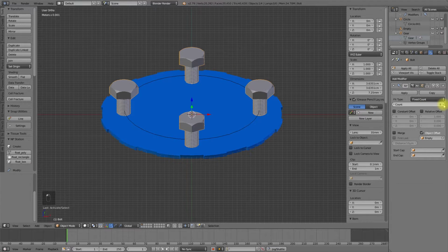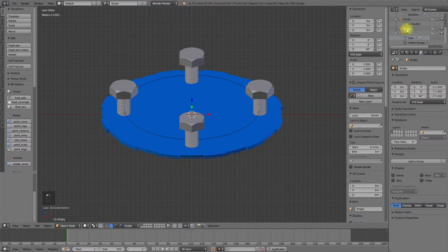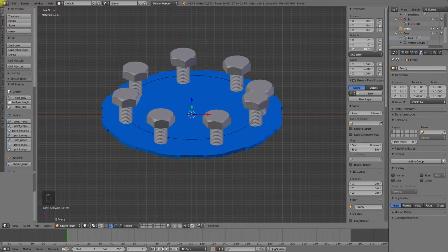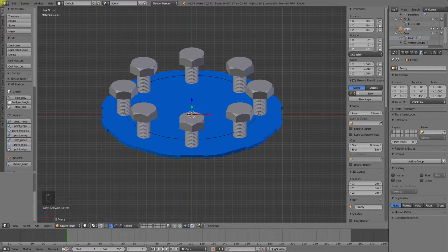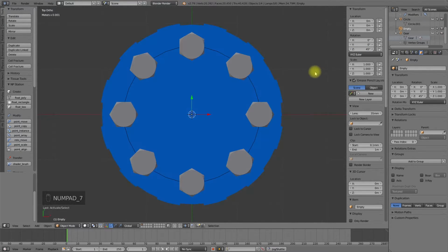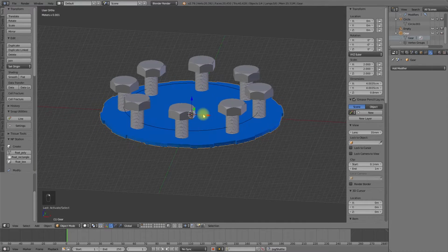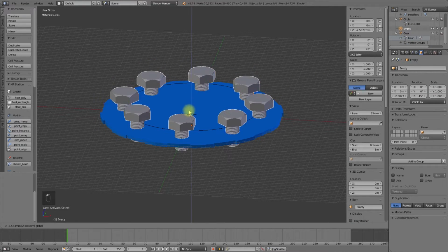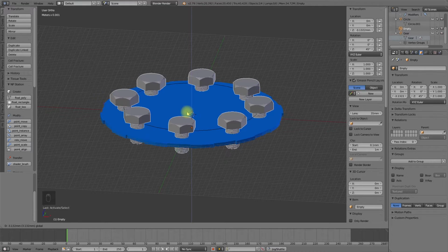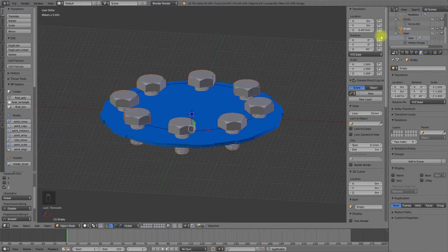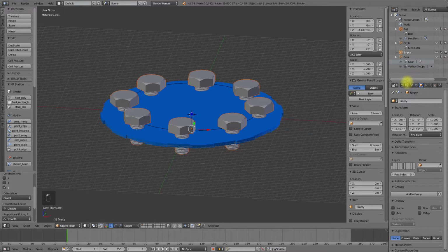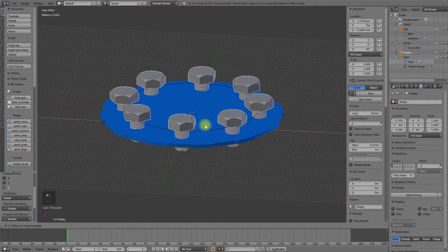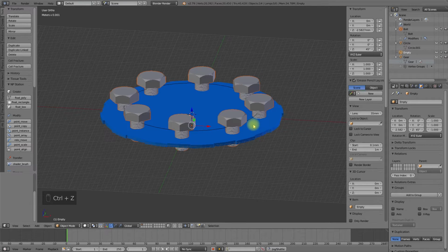If you rotate the reference object, in our case the empty object, the additional instances of the bolt object will rotate around the origin. Rotate the empty to a value to position the array instances precisely onto the given circle.